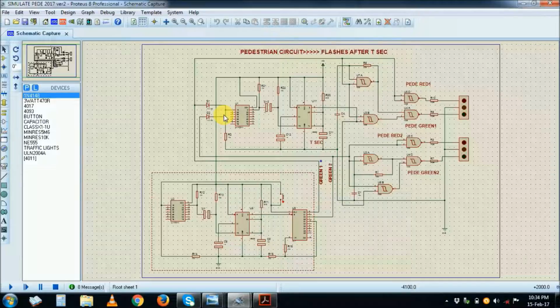to simulate the green signal going into the pedestrian circuit, and you see it is exactly the same circuit like the practical circuit, only that here we are not having a driver, we are having simulation lights, the center light being off, wired to ground, because you need only two lights, the green and the red.